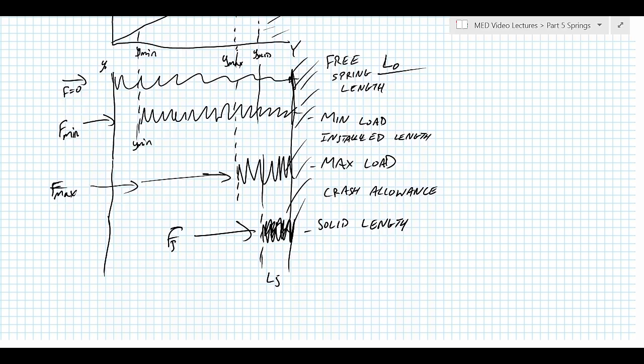So the maximum, that basically means that between Y min and Y max here is the working range of our spring. And our design practice is basically going to be setting up how do you find that working range and then pick a spring appropriate for the situation. All right, so that's the deflection side, and then there's one more thing we need to be specifically concerned about when it comes to compression springs.